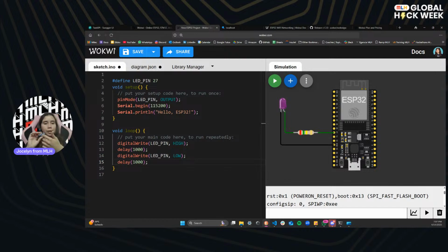So that's why you can measure distance depending on the time spent going in one direction and then coming back to the eyes of the ultrasonic sensor. If you can see, this sensor has four legs: the ground leg, the voltage pin, and then the echo and trig pins, which are two digital pins that will help us read all of this information from our sensor.